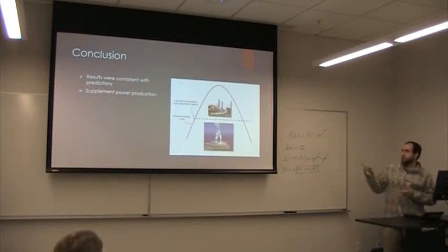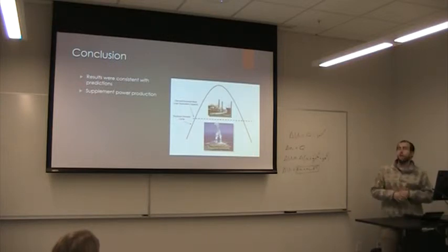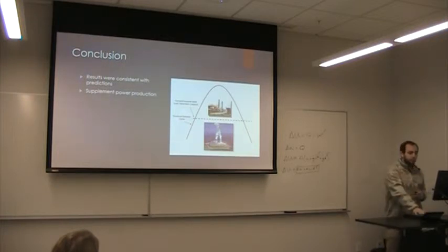Steam turbines are what's generally used for electricity production, but during peak times those systems can't handle the demand that's needed. So these gas turbine systems are used to supplement the electricity production for that given time. Once the demand falls back below the threshold that the steam turbines can handle, they shut down and are not used again until they're needed.